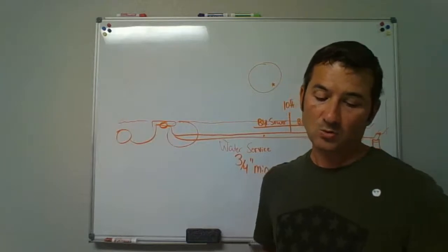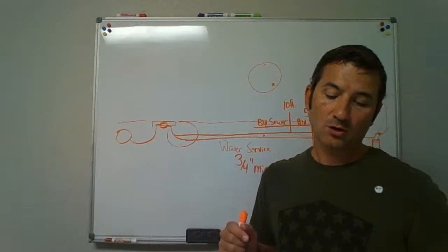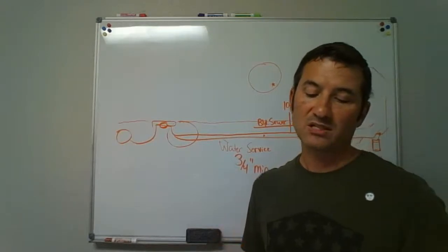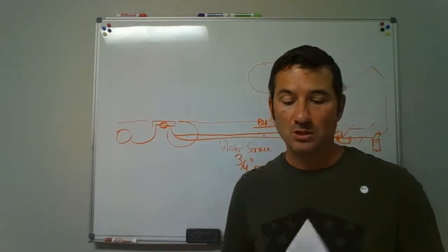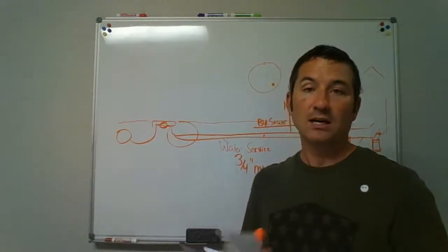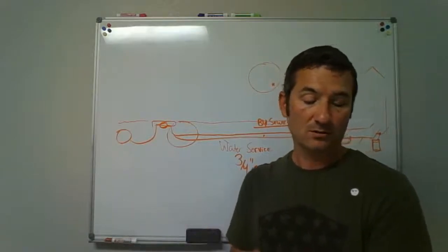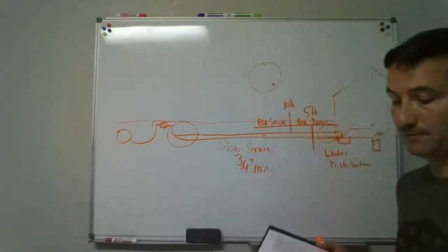It says where the water service is in the same ditch, the sewer needs to be constructed of materials in 702.2. So you'd have to flip over to 702.2 and look at the chart there and find the materials. Here it is, page 60.